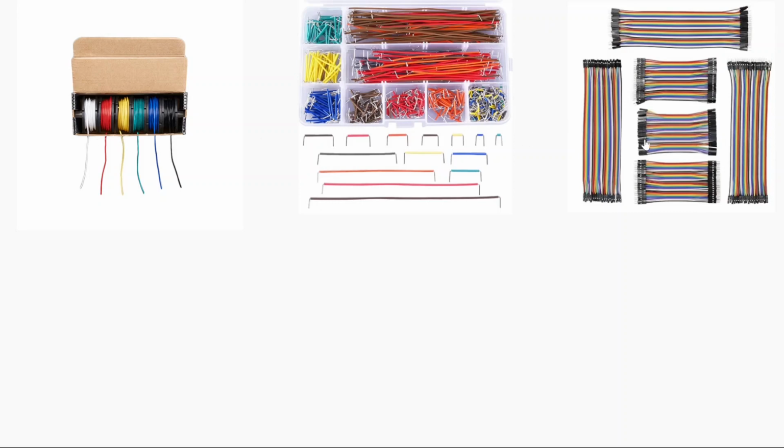In all of these three, for students to get really quality skills, and to be ready in almost any working scenario, it's recommended to use the tools: the cutter to cut the wires, and the stripper to strip off the ends, because these others are already pre-made. You just have to place them onto the breadboard or the prototyping area, whereas these spools will really give you the skills required to be ready even for conventional working environments.